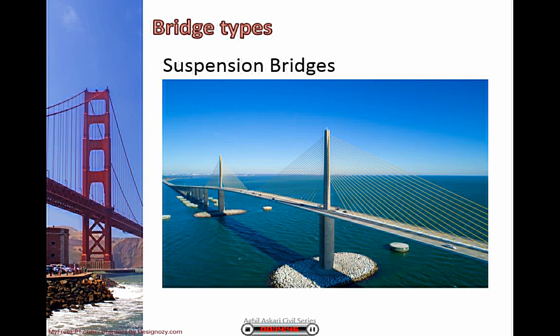A cable stayed bridge is dependent upon towers or pylons, which are the load-bearing element of the structure. Cables are connected from the pylons to the deck below, either directly from the top of the tower or at different points of the column. When connected at different points of the column, this creates a fan-like pattern. This is the feature many people associate with cable-stayed bridges.